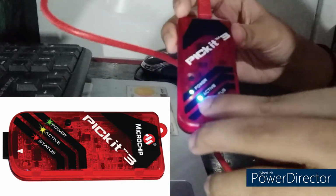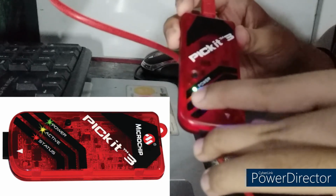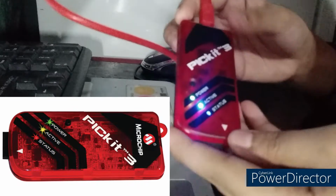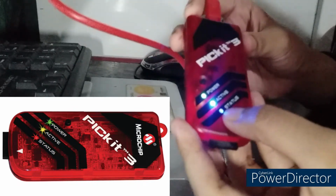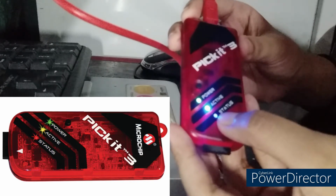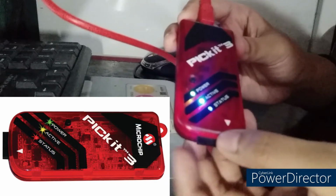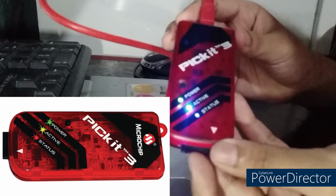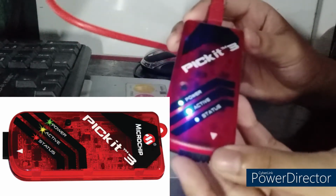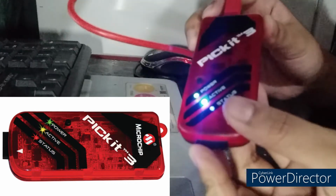So for the blue color here, it means active, meaning it is connected to the PC USB port and the communication link is active. So it means it is functioning well. And then our third color here means our status. Okay, so if it is green, meaning it is ready to start or it is a successful completion of our code, and then if it is orange, meaning it is busy with a function in progress. And third, if it is red here, it means there is an error occurred in our code.